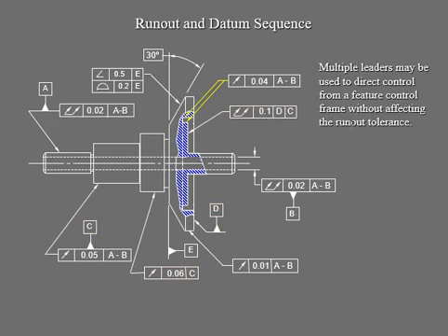Now let's go into the multiple leaders. Here we are using two leader lines right there. And for this circular runout, it's showing you here and right there. You can't see it very clearly, so when you study, make sure you make it really big for this position, so you can see the surface, which surface we are identifying for this runout, or controlling, I would say, with this tolerance 0.04, and that's your combined A and B.